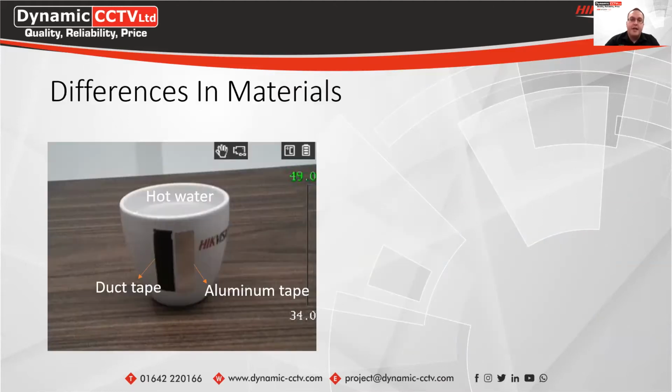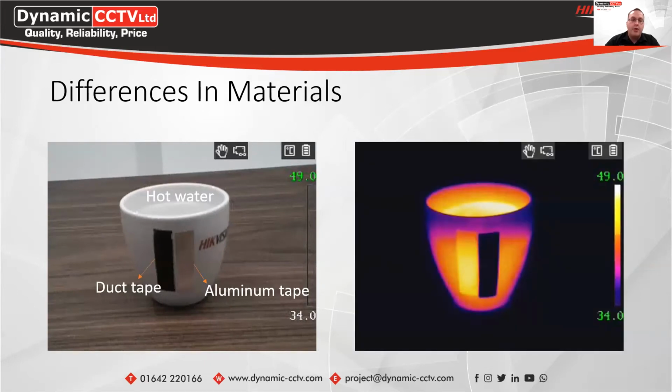There is a difference in materials depending on what kind of object you're looking at. Comparing duct tape and aluminium tape, you can see the duct tape showing hotter than the aluminium tape. This is to do with the reflection and absorption of the infrared radiation. This comes into the emissivity ratings of different materials, which we have a table for in a couple of slides, and we'll go through that.